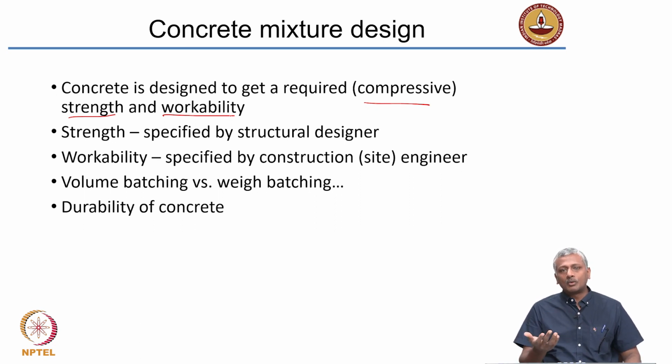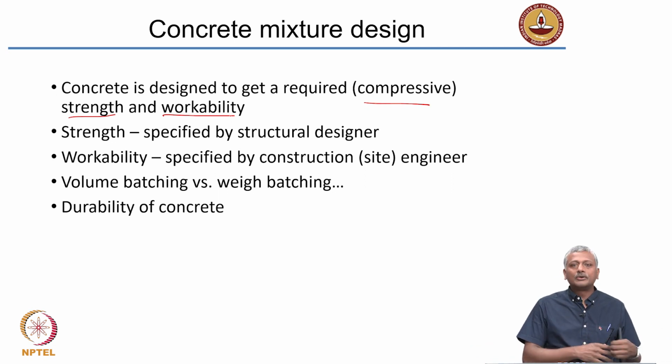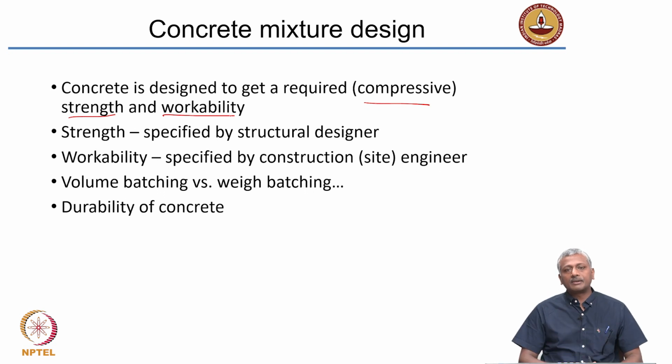If you add the right amount of water, you get the correct amount of workability. If you add too much water, the ingredients may start separating out. If you add too less water, your flowability or consistency may not be enough for the concrete to satisfactorily fill up the formwork. Okay. So, who does the decision making as far as these characteristics are concerned?